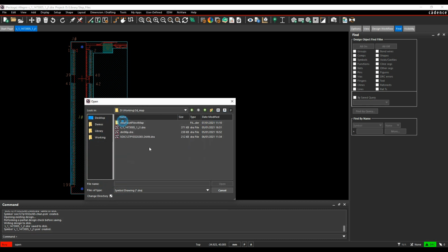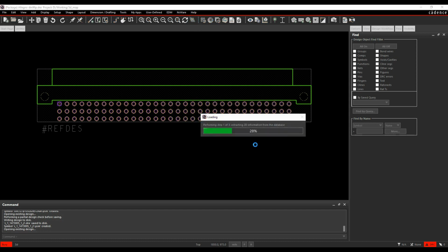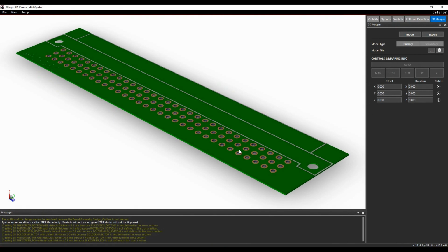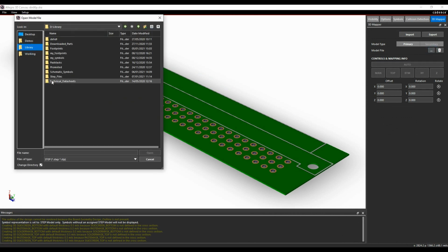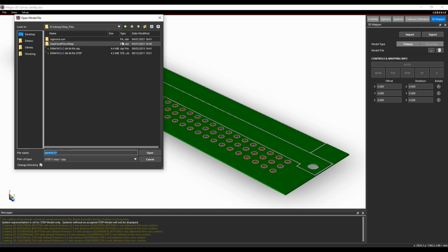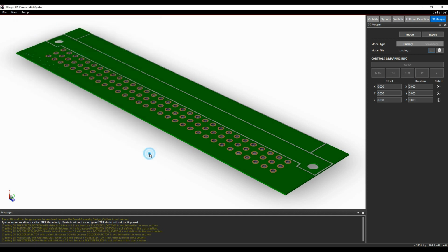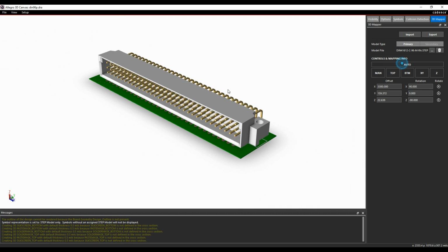So I've got a DIN connector, standard kind of through hole connector, 41612 style, 96 pins. I've got all these holes here, so let's go to the 3D canvas. I get the holes. So what we can do is go to the step model again. Use the filter. Again, different rotation, so we'll try the auto button.